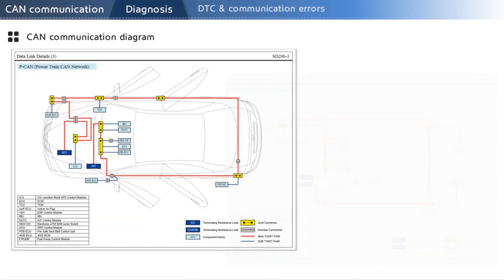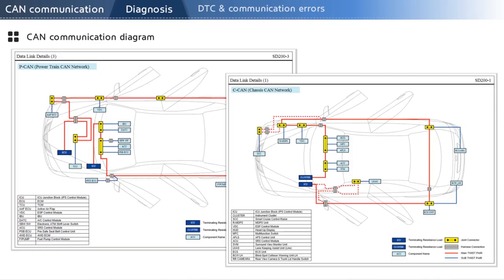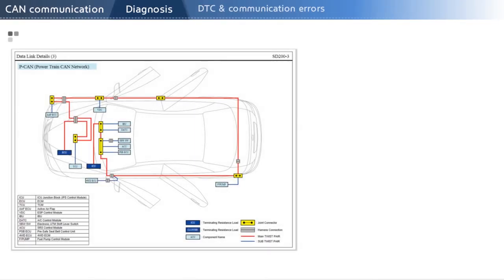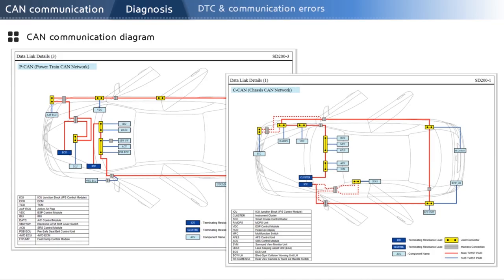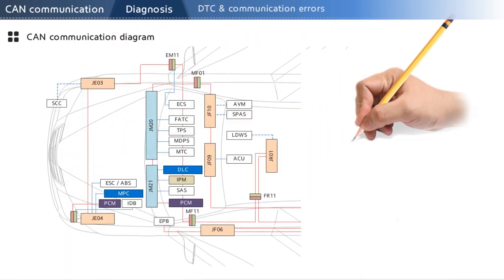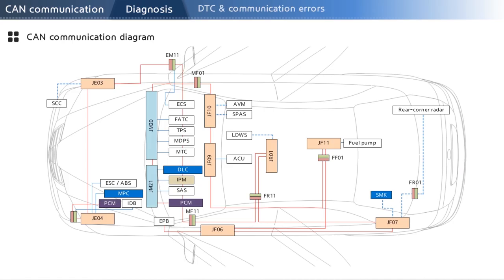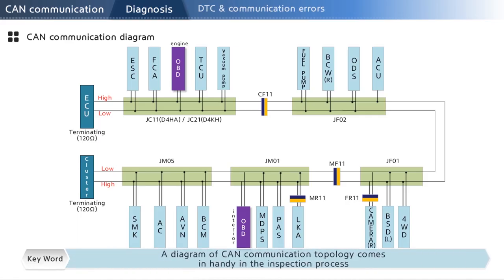The CAN bus is the connection of all controllers in the entire vehicle in a highly complex layout. This is why visualizing the layout by drawing a simplified diagram is necessary. Having a topology diagram of CAN allows you to identify each controller connected to the interior and engine compartment connectors. It also helps you remember the location of the intermediate connectors as you remove them.